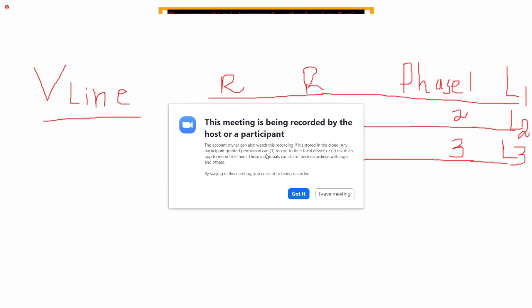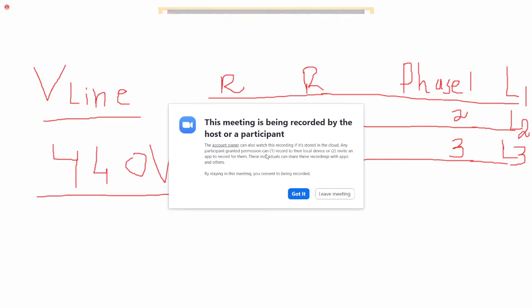Yes, sir. Okay. And again, I will tell you, it's 440, and merchant ships are also generally 440. Whichever ship you go, generally 440 volt line voltage. In India also it is 440, and merchant ships are generally 440. If you visit the switchboard of a merchant navy ship, you will see 440 volt written on the switchboard. That means one phase, second phase. If you put your multimeter, there is a voltage of 440. So I believe that line voltage is very, very clear to you.